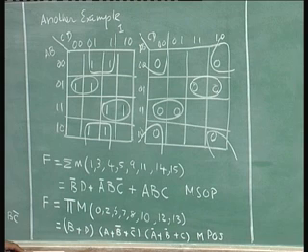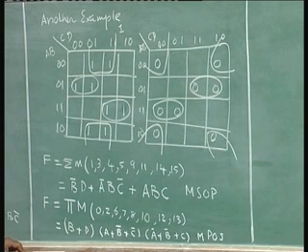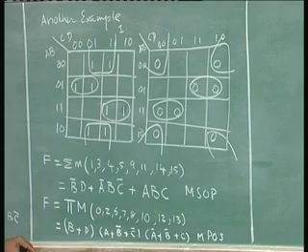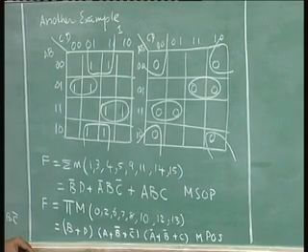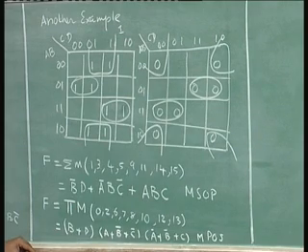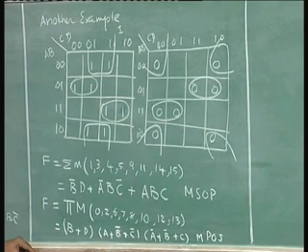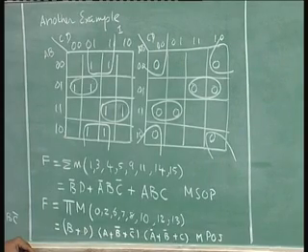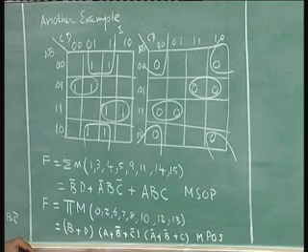You have a choice of using this or that, or if you are given a constraint as use many AND gates, only one OR gate, you will use this. If you are asked to use many OR gates and only one AND gate, you will use this. Sometimes these restrictions come in the design because of the availability of parts, because of the matching with the other part of the circuitry you are designing, because you may want to have an inventory of parts of the same type for different designs and different implementations. There may be several reasons why you want to go for this or that.